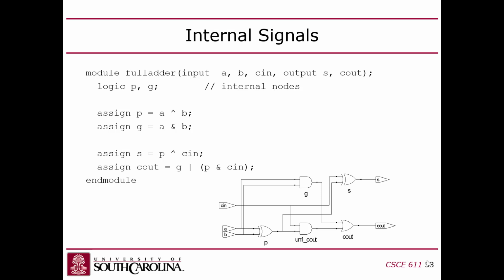When you simulate, these create event lists. So anything here triggers that, and then G changing will trigger that line. So everything is based on triggers. If any of my inputs change, it triggers the output to be updated. So instead of statements being executed in program order as you have in Java, it's all based on triggers. Any input changes, it triggers that line of code to execute, and it executes immediately.